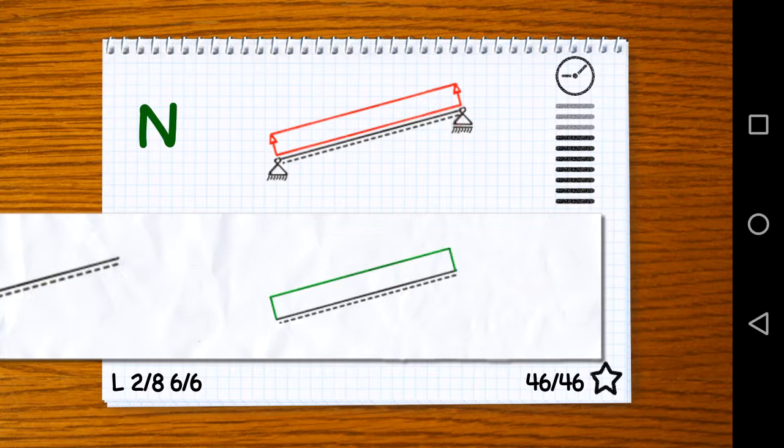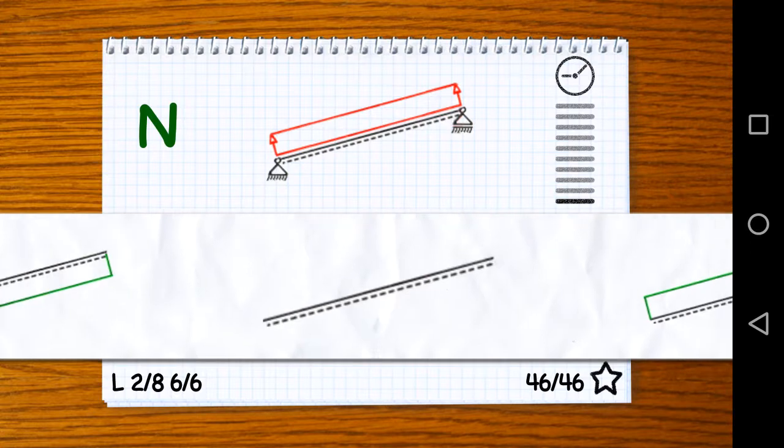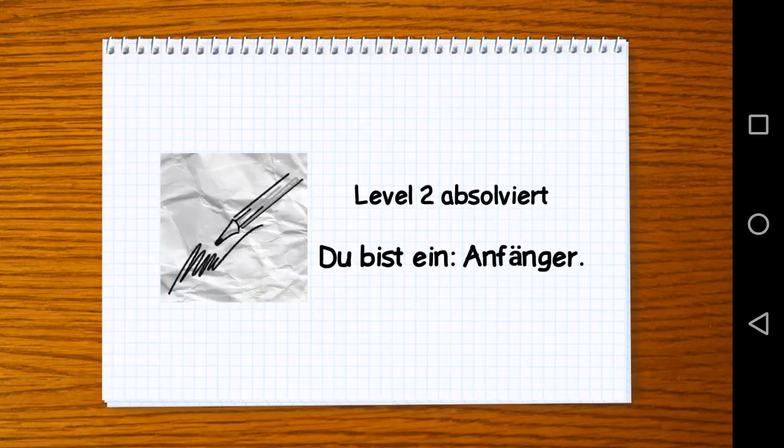I said something similar a while ago, but look at the position of the support here. That's the main part. So if we do balance of momentum at the pin support, we're going to find out that the roller support needs to have a force acting downward, a vertical force acting downward, and that vertical force is going to put this beam under compression. So it's compression. It's not zero like in the middle, it's not tension like on the left, it's compression.